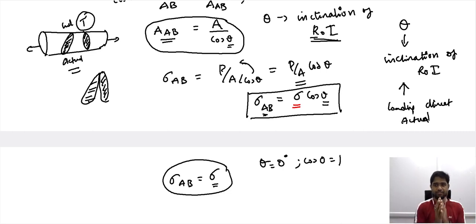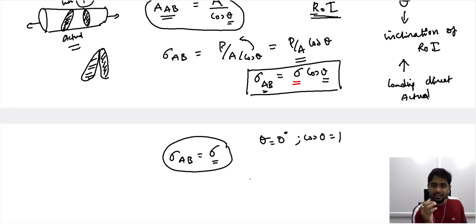So what essentially we have done is we have now been able to express the unknown actual loading condition in terms of the known test condition. That is what we have been able to describe. Again, I spoke of the response of the material, because this can also be considered as the response of the material, because stress is nothing but the resistance offered by the material for the imposed loading condition. So in that way we are now able to describe the resistance offered by any inclined plane within a three-dimensional system to an imposed loading condition.